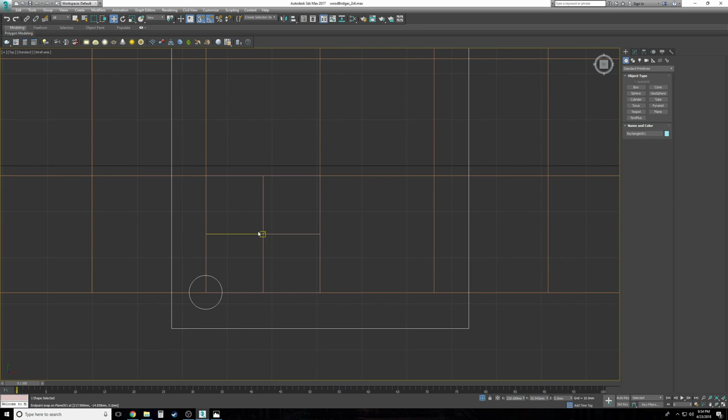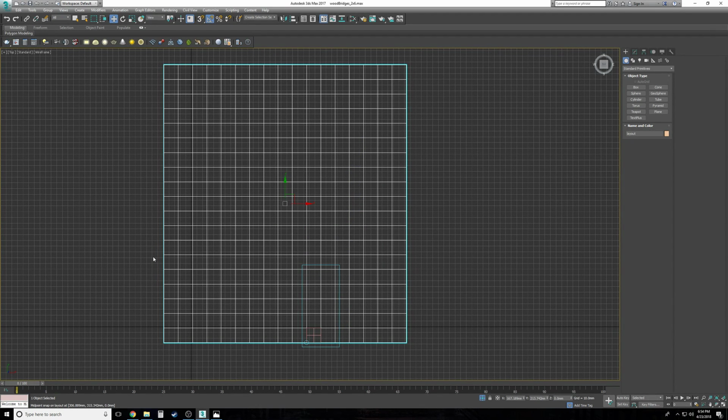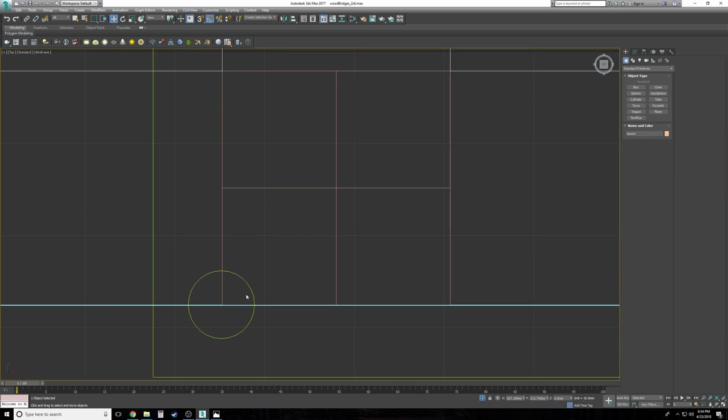object, something to align to, because right now you can't align to this thing. The only way you can align to this is the outer dimensions. You can't isolate just to this point right here. It will not work that way. You can't just go, I want to align it to this spot. It doesn't work that way. You have to have a corner, a point, an end point, or a midpoint, or a center. That's how alignment works. You also have pivot points, which you can get into later. You can actually go in there and customize where the pivot is and align to that, but we're not going to get into that.